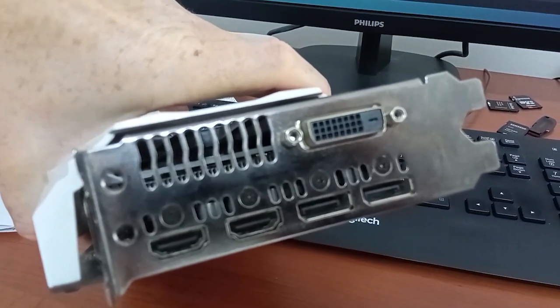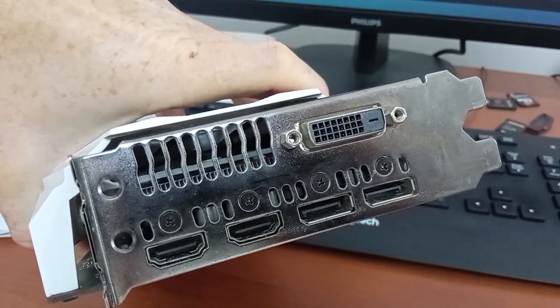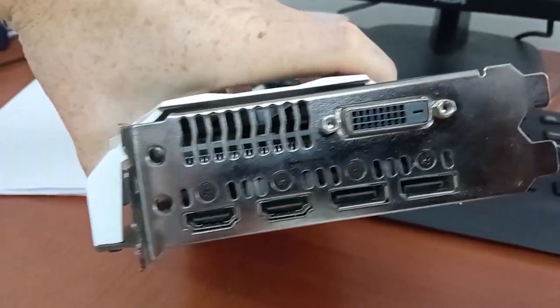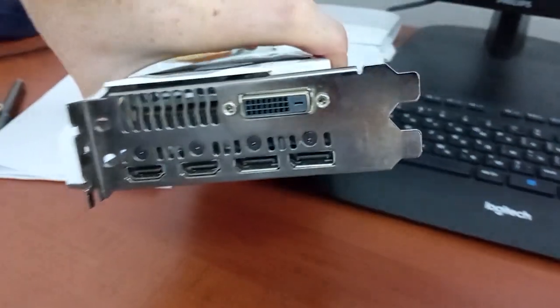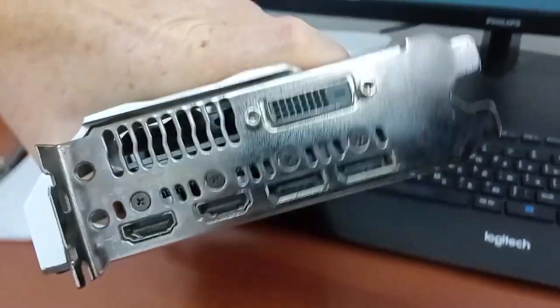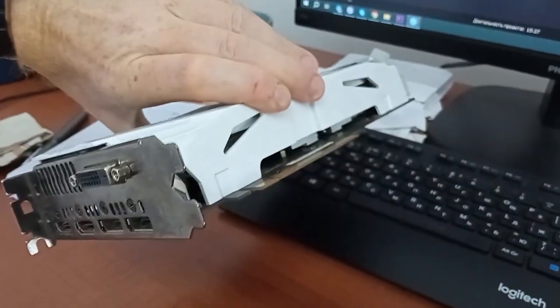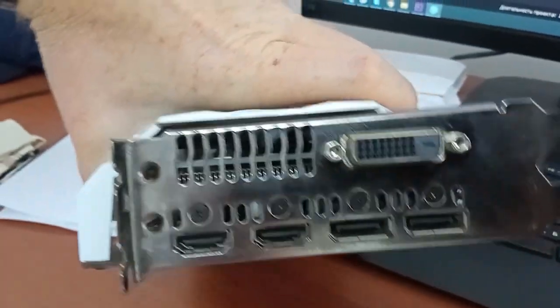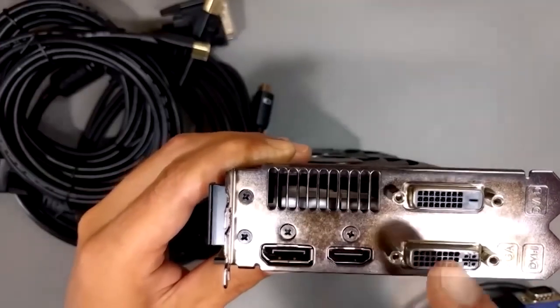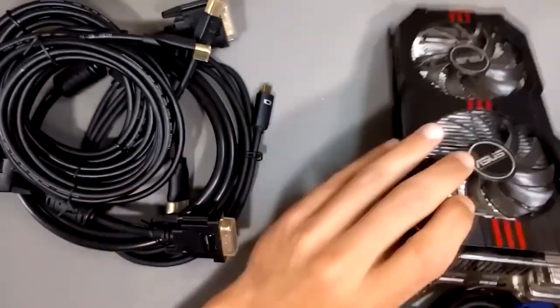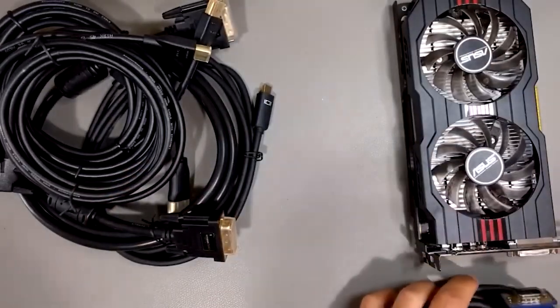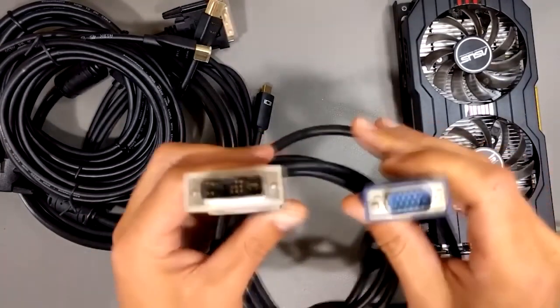Talking of compatibility, graphics cards that only have an analog DVI-A port don't support monitors compatible with the digital DVI-D standard. Since such monitors don't have an analog interface and their cables can't work with digital signal, it will be impossible to receive video images even if an adapter is used. This situation can be compared with attempts to connect a modern TV to a VGA port on an old computer. However, special converters can transform DVI-A analog signal into DVI-D digital signal.